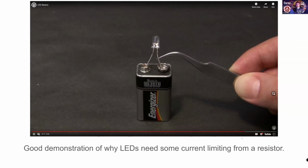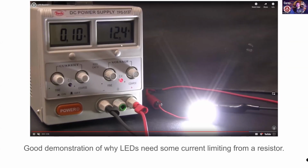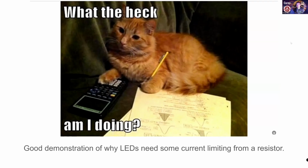But then let's see. So here's a larger module. This is a large module that's designed to run at 12 volts and 100 milliamps. But the average LED, like these guys, these are set to run with a target current of 0.02 amps or 20 milliamps. So you should expect any LED that I've handed you to have a desired current of 20 milliamps or 0.02 amps. Those are the same thing, just different scales. So that's really a useful piece to know.